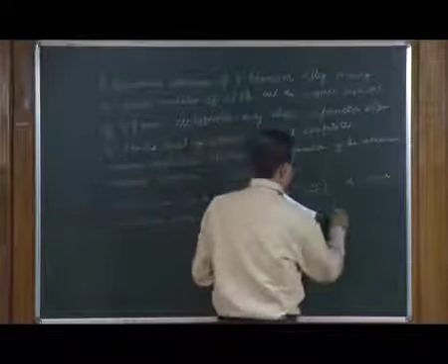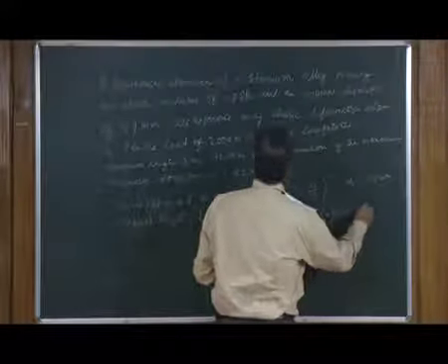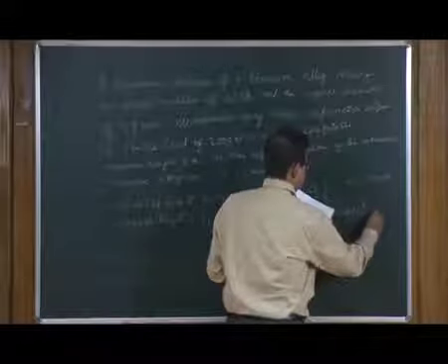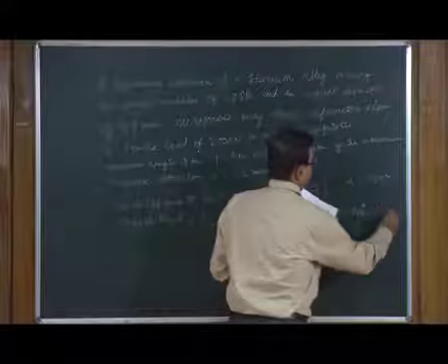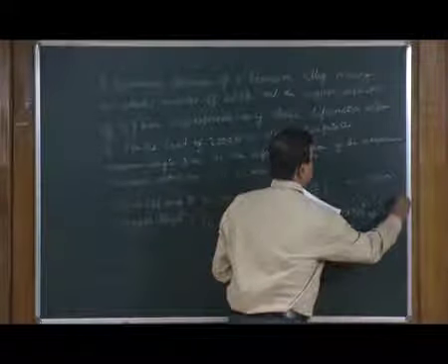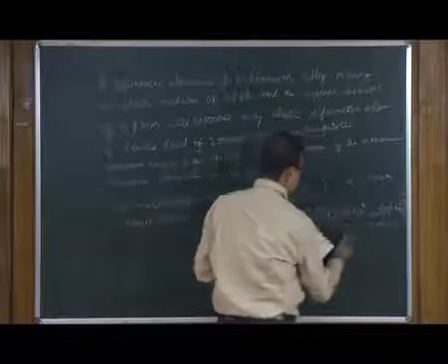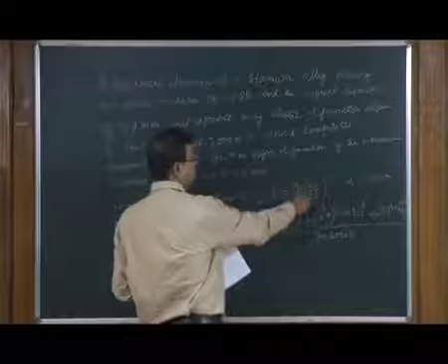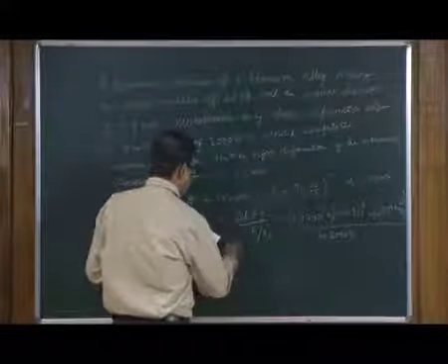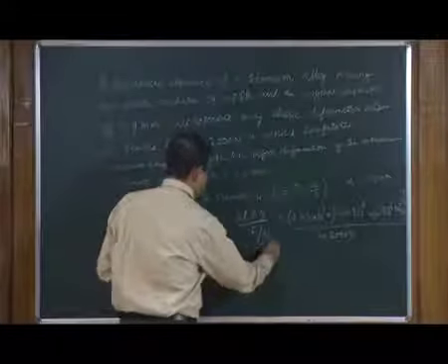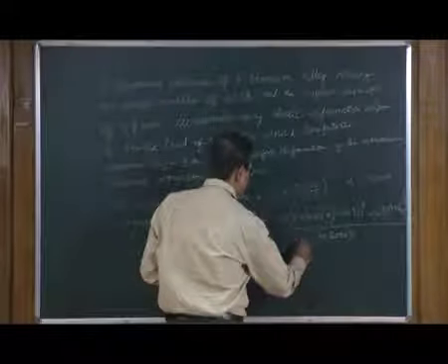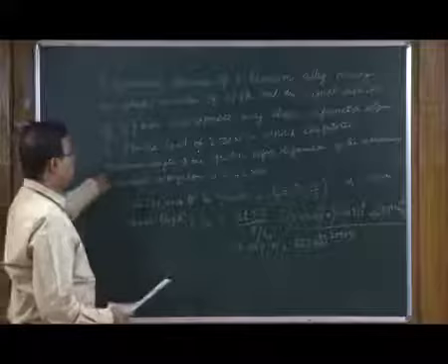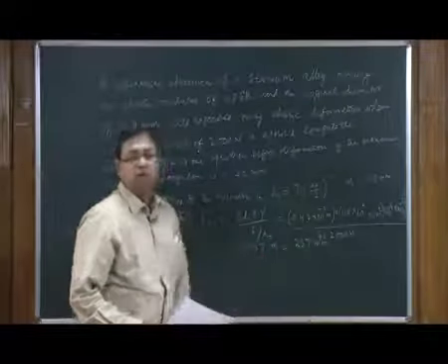So, this is my elongation, this is my Young's modulus, then there is a pi, and then there is a 3.9 into 10 to the power minus 3, there is a square there, divided by 4 into 2000 Newton. So, this 4 is coming because there is a d0 square by 4, and if you calculate that, this becomes 0.257 meters, which is equal to 257 millimeter. So, this is the maximum length of the specimen before it starts deforming.